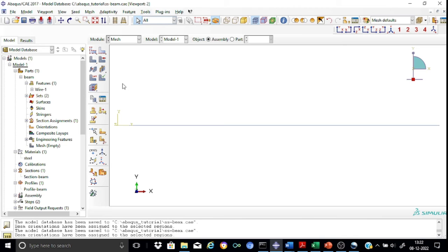The accuracy of the Abaqus results entirely depends upon the meshing procedures, the element type selected, and the strategy you have adopted in performing the meshing operation on a global part or a local part. In this case, our beam element is a simple element, so we need not break our head over the meshing. It's a very simple procedure.